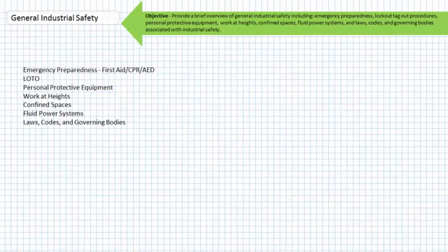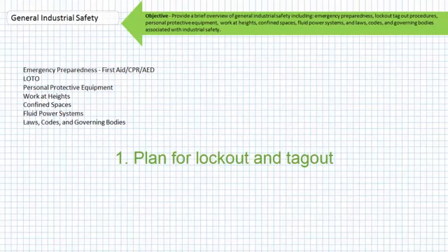The general procedure used to prepare a system for service follows this scheme. You might see textbooks or attend safety certification training that uses more or fewer steps, but they follow the same general sequence. Step 1. Have a plan. Know where all the lockout points are on a particular system and have the means of locking them out available. Your company should have procedures clearly indicating what needs to be locked out prior to performing a service. The workforce should be trained in the use of lockout and tagout procedures.